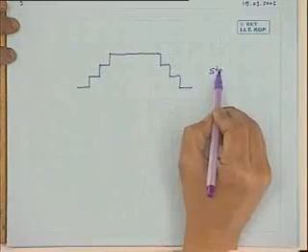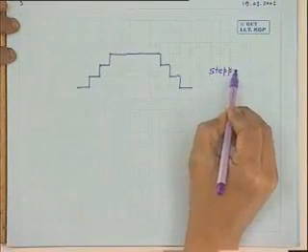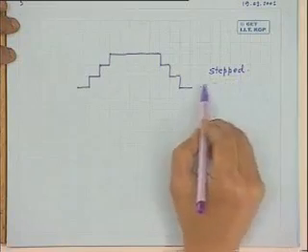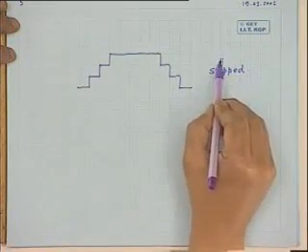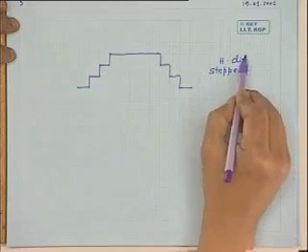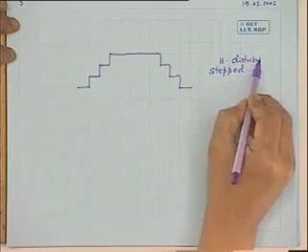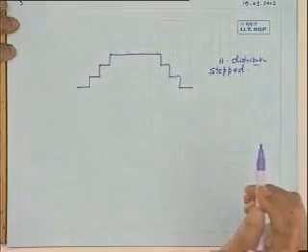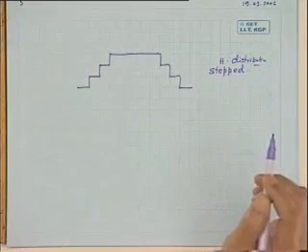Therefore, the point I want to tell is that when you use a single coil, it is rectangular in nature. Otherwise, if there are several coils which are distributed and connected in series, the MMF or H distribution will be stepped in nature.